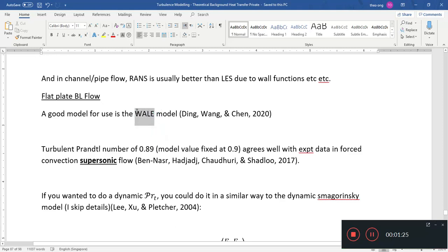I've gone through this in a few videos prior. This is pure LES. This model basically acts as an advanced kind of Van Driest damping function that helps you get decent resolution and decent wall behavior near the wall, as compared to the Van Driest one anyway.